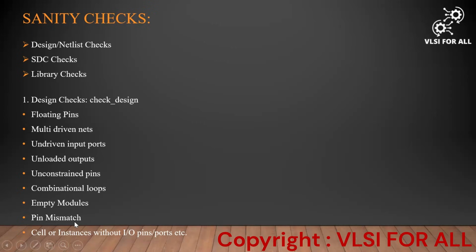What pin mismatch means is that in a design they have input pins and output pins, and some are input and output pins. In some cases, whenever an input pin should act as an output pin or vice versa, if it is not acting properly, that will be triggered as an issue, a design failure issue. And the last one is cells or instances without IO pins or